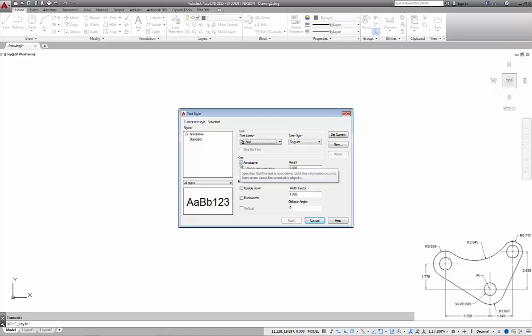And when we know specific height and specific size drawings, we don't necessarily have to change it, but when we're dealing with larger scale drawings or larger drawings in itself, it's a good idea to use the annotative style, because you're not sure when you start what scale that output is going to formally be. And so it's hard to control your text size because of that.